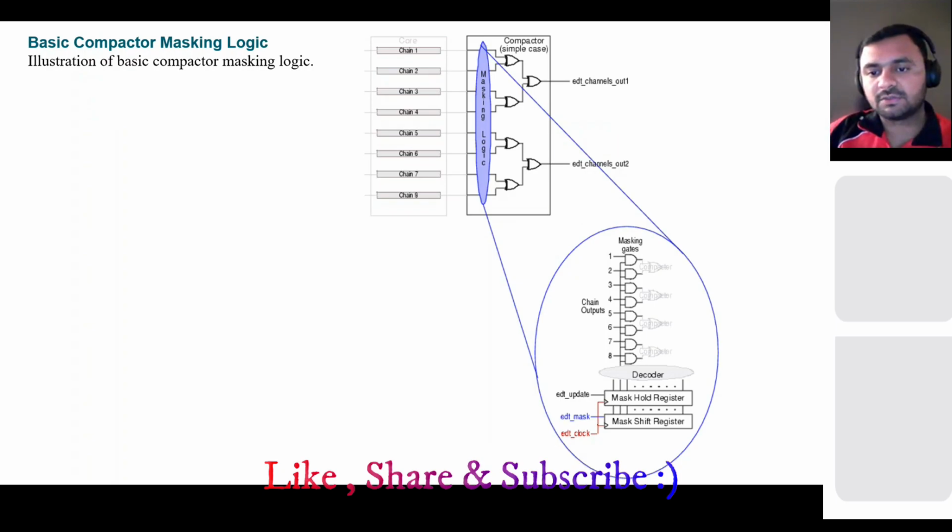And this is your masking logic. As I told, in the masking logic you have a mask shift register, a mask hold register, and then a decoder. Basically, masking logic is nothing but an AND gate. Suppose one of the inputs is coming from the chains, and for the second input, the decoder will make it a 0. Since it is an AND gate and one input is 0, the output will always be 0. So basically you are masking it; you are not allowing this gate to propagate the signal. Here you will get a 0, and based on that it will proceed to the other logic.